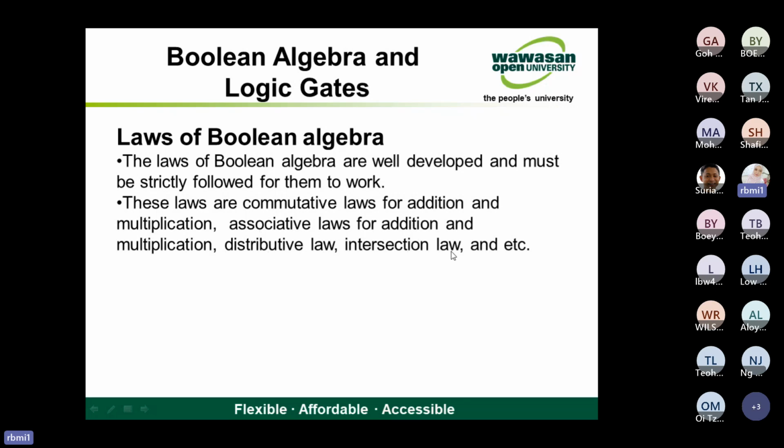Boolean algebra allows the systematic arrangement of logic gates to produce the desired outcomes. We use Boolean algebra to get the simplest circuit. We do simplification: we want to construct a circuit to perform a task with minimum logic gates in order to minimize the circuit. We don't want the circuit to become complex. The number of gates used will ultimately translate to cost. More logic, more components, means an increase in cost. The fewer the gates or components, the smaller the cost, and our system will be less complex.